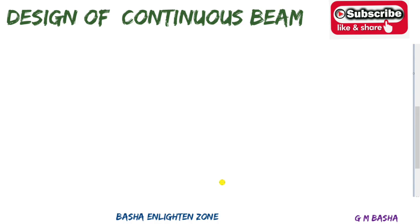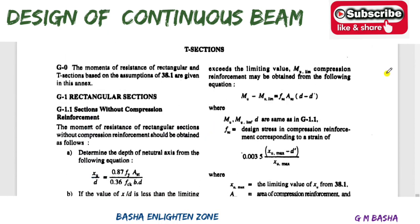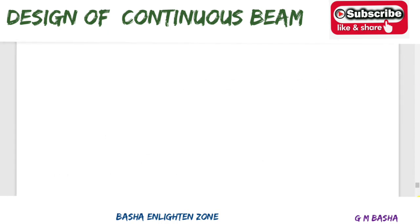Then after obtaining this, your next step is providing shear reinforcement. So we know the condition for providing shear reinforcement. So how to provide the shear reinforcement? First calculate the value of tau v, which is Vu by bd. Generally for a simply supported beam, Vu will be calculated as WL by 2. But here for Vu also there will be standard coefficients. See again in page number 34. So we are in which page number?